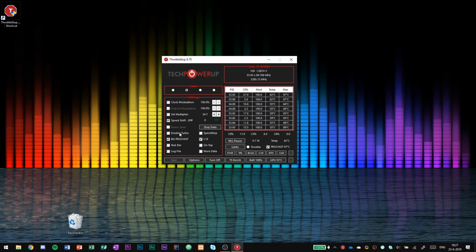It basically reduces the amount of voltage that the processor can draw, and it is the main way to do a little bit of power limiting. Then there is disable turbo. Like I said, you can disable the turbo. It is a short burst of speed that usually happens when you're launching applications. For that 10-second period, it will up the core voltage and the speed, and that will allow the processor to have a short burst of a lot more speed that you will notice, and it is used mostly for application launching. And when the application is launched, it will slow down back to its base clock again.